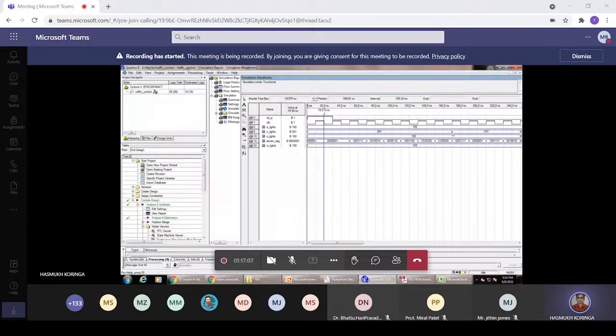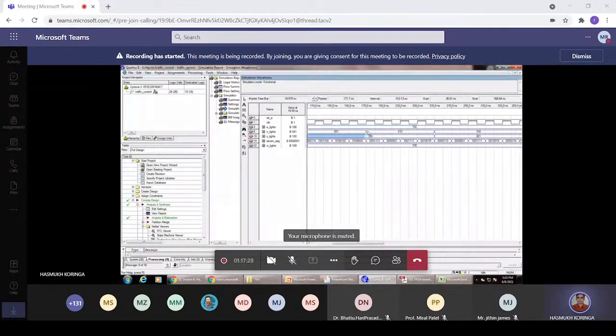So for the 8 clock pulse, this n_light output is 001, meaning the green LED is 1, and for the rest of the directions the red LED is 1, right? After the 8 clock pulses, it goes into north_y and stays for 4 clock cycles. We designed it to stay in this state for 4 clock cycles to give the holding, right? So here you can see the north LED output's middle bit is 1, and the red and green LEDs are 0.